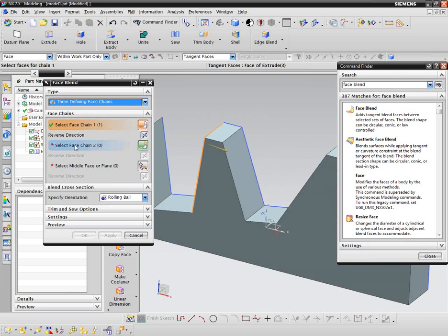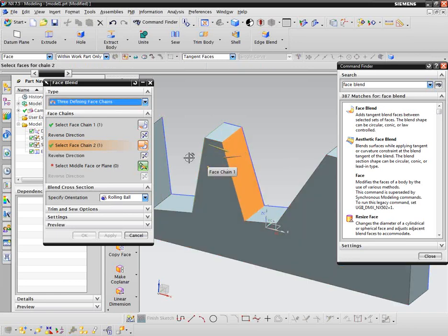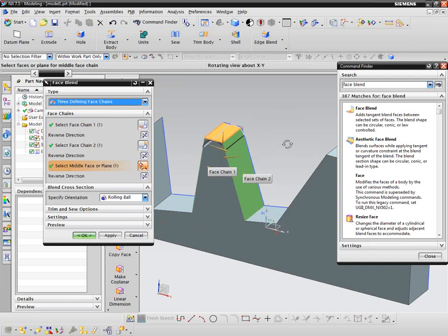And then you either choose this next star. The red star tells you that it needs to be completed. If you don't click it, you can middle mouse button click, which I'll do, to go on to the next step. But if you don't, then you keep selecting faces incorrectly. So this one also faces in, so it's oriented properly. Middle mouse button click. And then I'll choose the top surface that's the middle and correctly pick that.